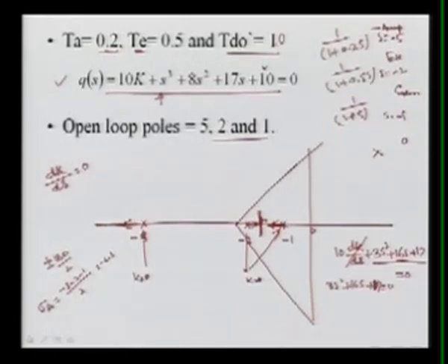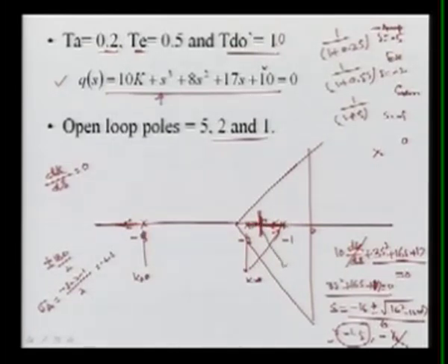If we solve this quadratic equation, we get s equal to minus 16 plus minus the square root of 16 squared minus 12 into 17, divided by 6. Finally we get the value minus 1.5, and the other value is minus 4 or something, which is not possible. Only this value is the break-even point, the one leaving point. It will be between minus 1 and minus 2, because the other value is not valid. So they will leave in the intermediate of these points. It is the point minus 1.5 here, they will leave at 90 degrees, and finally the movement will be like this.